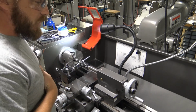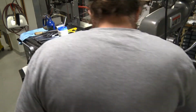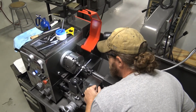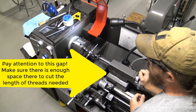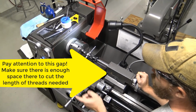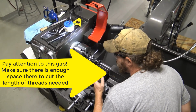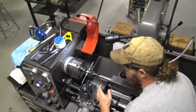I use my body weight, and I just put my palm here and lean into it, putting pressure on that die. If I don't do this, all I'm going to do is cut one circle around the edge, because it's not going to want to grab into that material. So I'm putting most of my weight onto this, pushing it forward into the chuck, all right?